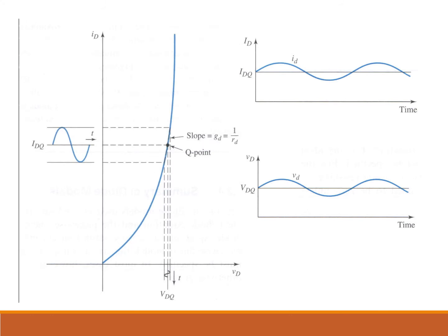The Q point, or bias point, is used for a device like a diode. It means that we want the diode to operate at a steady DC input, so that at that point the diode can operate correctly without saturation when performing its role. For example, if the current value is from 0 to 10 milliampere, let's say that IDQ is 5 milliampere.